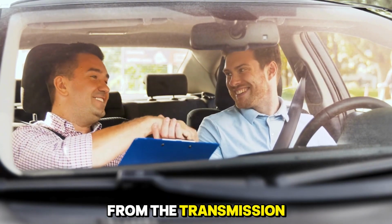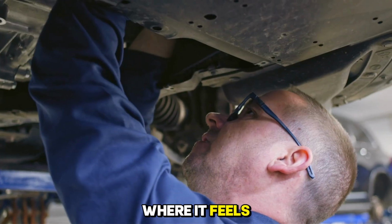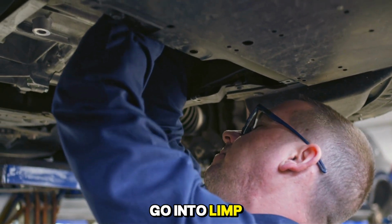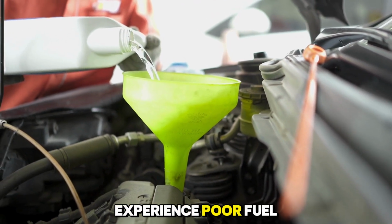Symptoms can range from the transmission slipping and not catching the gear to harsh shifting where it feels like the car is banging into gear. You might also see the transmission go into limp mode, where it stays in one gear to prevent damage, or you might experience poor fuel economy.